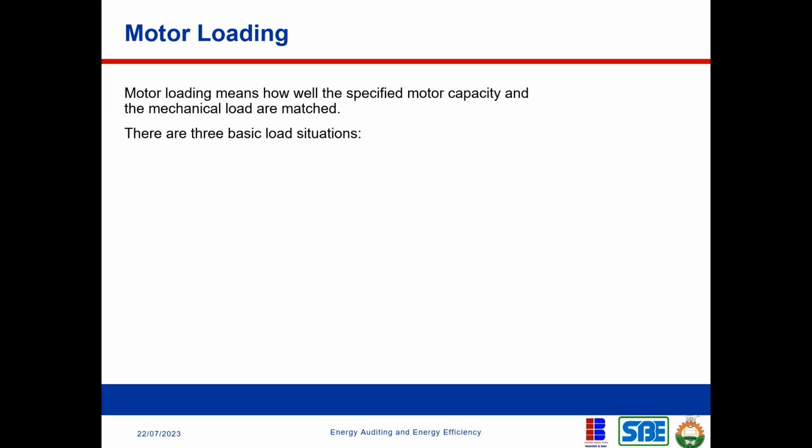So this is motor loading. Motor loading means how well the specified motor capacity and mechanical load are matched. If they say the motor can do 75 kilowatts of work, how much load is it doing? If you give it 20 kilowatts of work and the motor is rated 75 kilowatts, what is the percentage loading on that motor? Just looking at these 2 figures, you will see that the motor